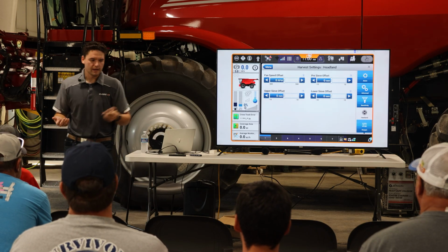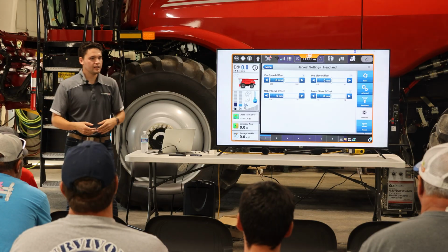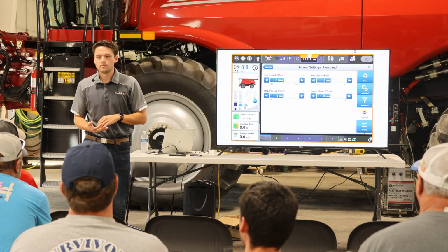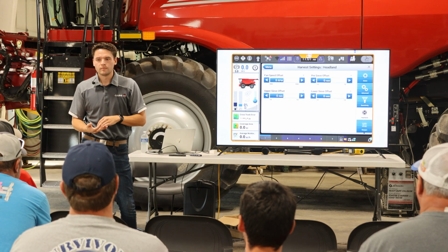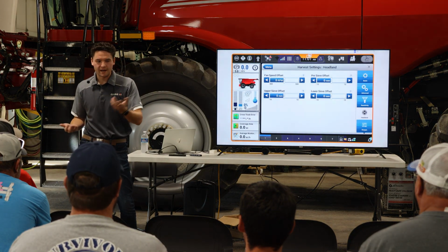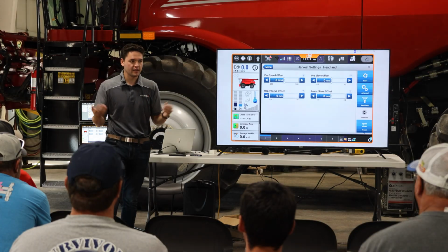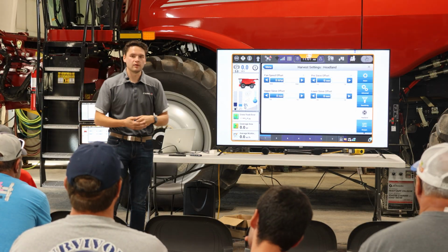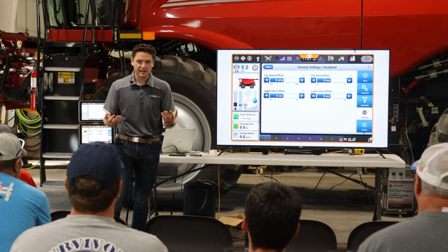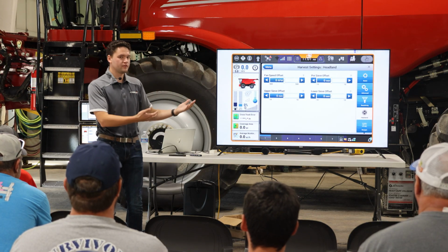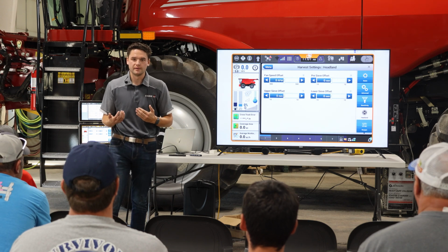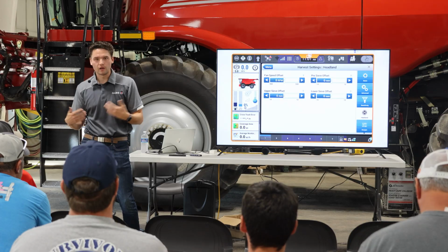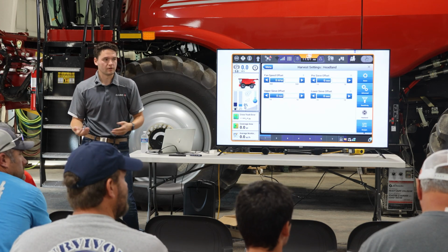Slow your fan down. Yeah, so when we get to the headland and we turn around, what usually happens? Well, why is that? Because we get to the end of it and we stop putting product in. As we stop putting product in, what happens to the load on the sieve? It becomes less, so therefore it's lighter, but our cleaning fan doesn't adjust for a lighter crop mat. So as it gets lighter, it starts blowing more out the back, and loss usually occurs on turnaround.